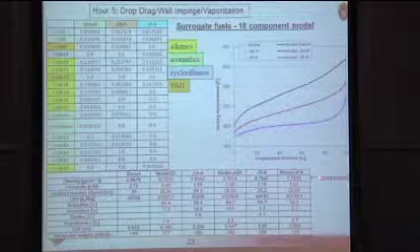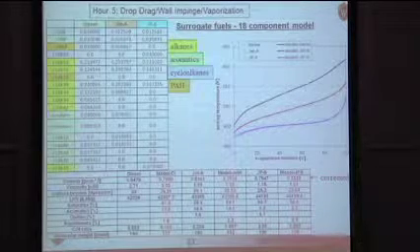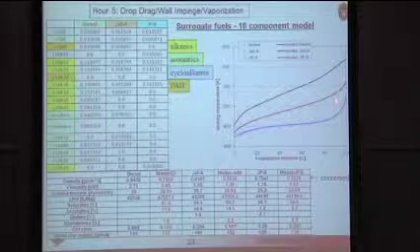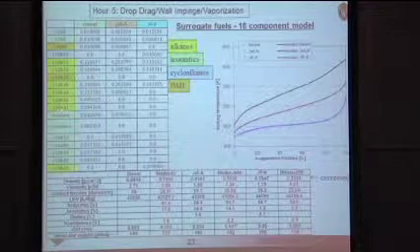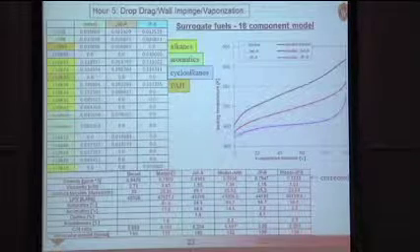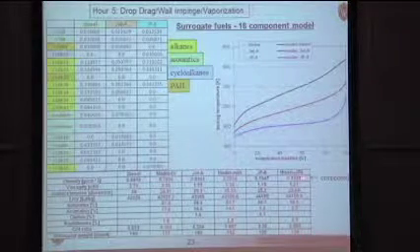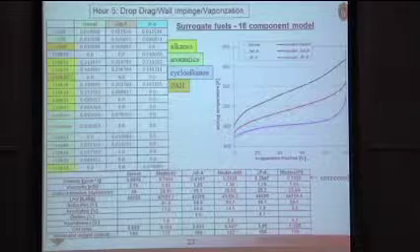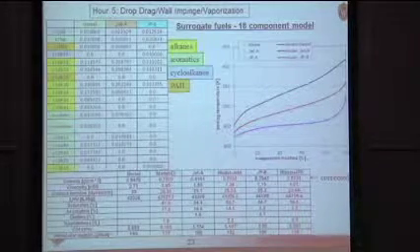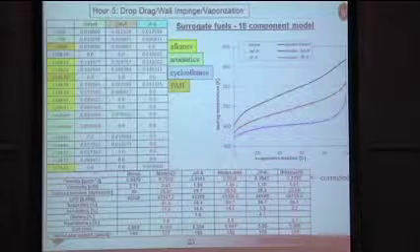Density, though, turns out to be lower for the surrogates, and that's because the realistic fuels typically have a lot of heavy species higher than C20, for instance, which contributes significantly to the density. So one way to deal with that is simply to correct the densities to make sure you're using the experimental density, or to add more species.